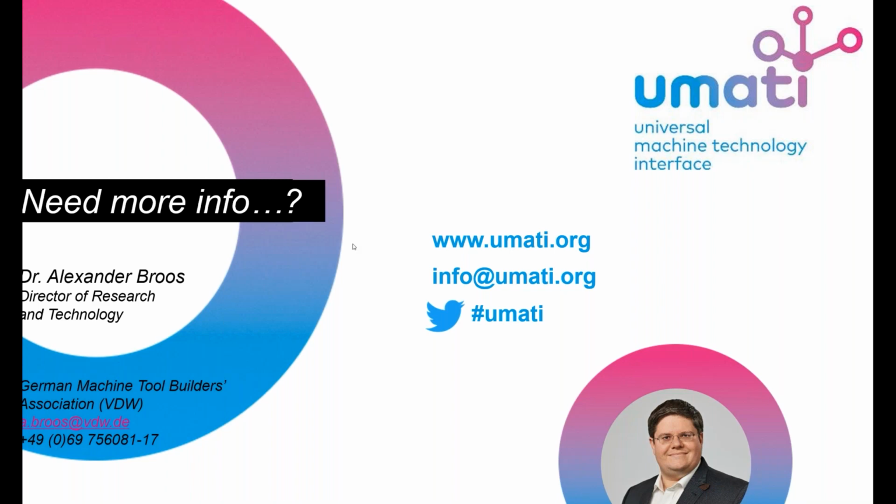You have to distinguish two things. The one is if you have an OPC UA specification, you have the dictionary and the semantics of the data you want to send out. The hard part that usually remains with the machine builder is that you have to come up somehow with the information behind those signals. So if you imagine you have a stack light, which is green, yellow, red, blue, whatever, and blinking or not blinking, you have to collect those signals within your PLC or within other controllers, and then somewhere put them onto a system where you can have an OPC UA server running that will then send the data out into the standardized format.